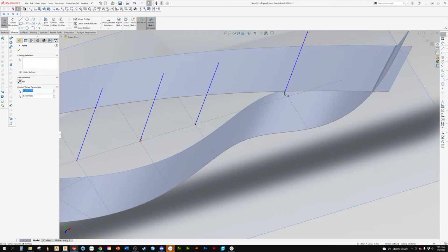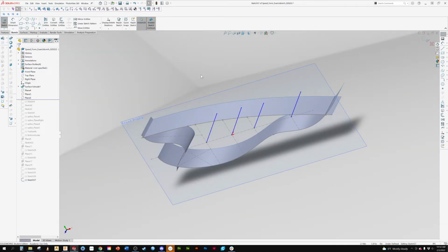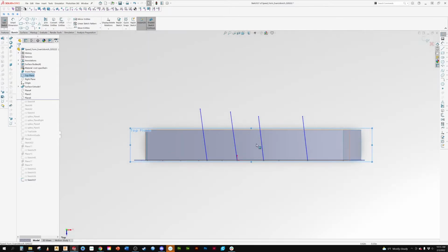This is where building surfaces has to be extremely detail oriented. If you don't build the surfaces and have the proper properties, coincidences, and snaps and all that, your curves aren't going to be right. And again, if your curves aren't right, your surfaces aren't right, and any surface that you build off of those surfaces kind of compounds it. So you really want to take time in this stage to build those curves right.